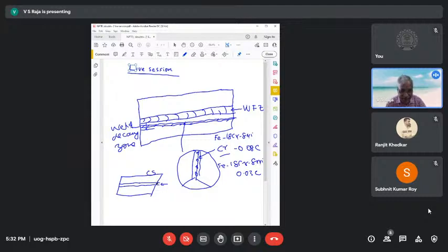Now the corrosion has occurred here. Obviously, there is a problem here. Why can it happen? It may happen for many reasons. One simple reason could be that the composition of this filler wire may be relatively anodic in nature. Suppose we talk about galvanic corrosion. Assume that this filler wire, whatever electrode you choose, is relatively anodic compared to this, then that can happen. But in carbon steel, it's very unlikely you see a huge difference in galvanic corrosion. But of course, if there is a problem here, then you can add a little bit of nickel, is a possibility, to make it noble.